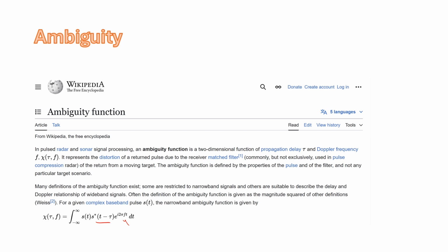If you wanted to measure that frequency modulation, you'd like the pulse to be long, which would allow you, in time or in Fourier space, to measure the Doppler shift. But if you make the pulse longer, then you'll get less range resolution. So there's this trade-off between the Doppler frequency resolution and the range resolution, which leads to this function being called the ambiguity function. None of that is central to our discussion today, except for the fact that we're interested in transformations of this general form, the Fourier transform of a function shifted relative to itself, which is mathematically what we'll call the ambiguity function. Here's the Wikipedia page where you could go read all about applications of the ambiguity function.